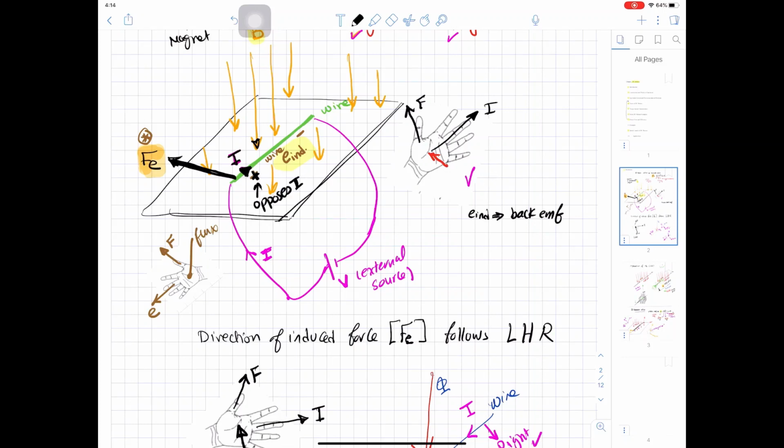So when you injected current into the wire, the reaction of the wire is generating a voltage against this current to stop this current from flowing. For the wire to generate voltage, it has to move. So you are getting the movement, or the motion, from the motor as a byproduct. This is not the main product. The motor is trying to react to the current by generating a voltage, and to generate voltage, it moves, which is good. We need it to move.